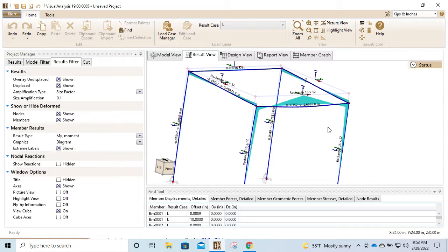So the last question. This might be a stair stringer type model, right? Where we have a stair stringer that's running up the stair angle, and it's flat at the top. I'm providing some loads on this stair stringer. So it's a 2-element, line element model. It's fixed at nodes 1 and 3. At node 2, it's free to translate and rotate. No releases though, so those 2 elements are fixed together, okay?